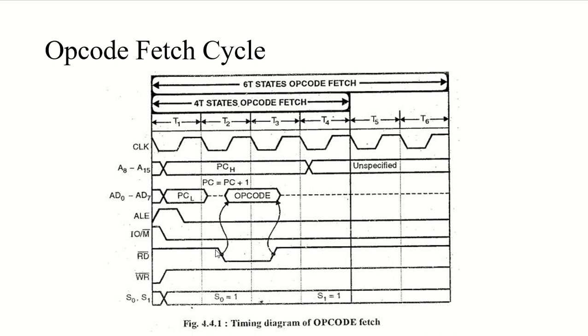During this clock cycle, the data from memory, like the opcode, is transferred to the instruction register. The RD control signal will be made high, and then RD will disable the memory device. Simple. And this is the only thing that is taking place right now.